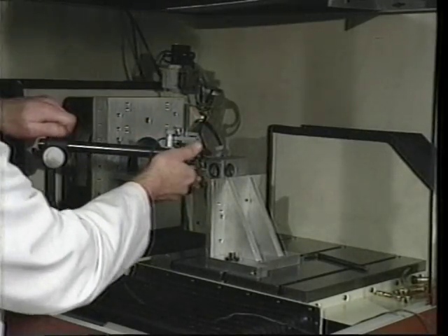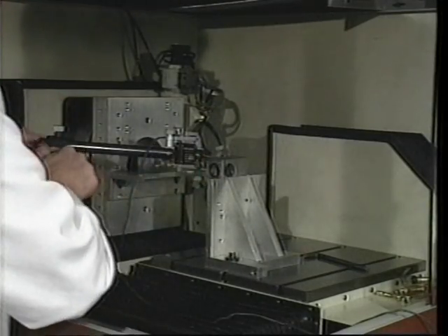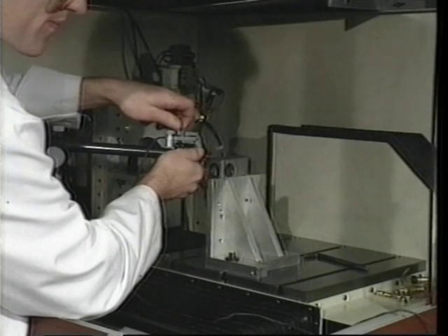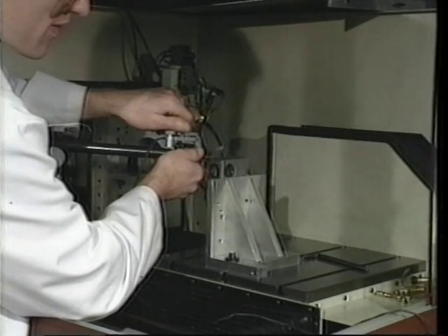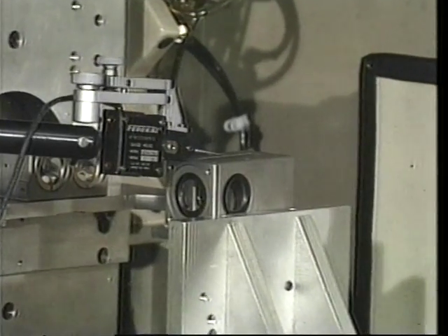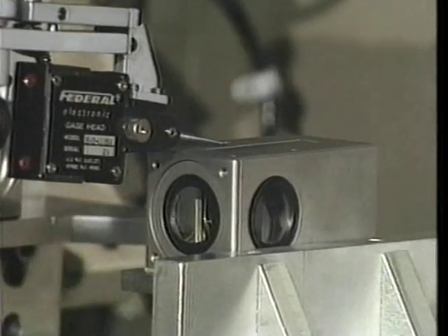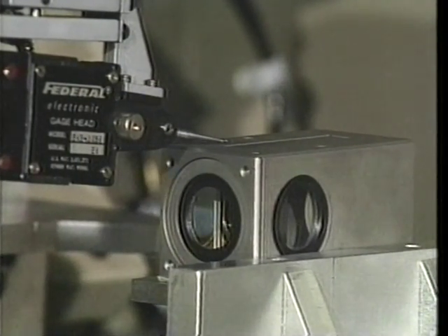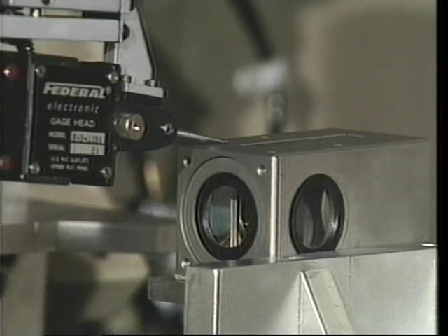The interferometer and reflector are aligned with the axes of motion in both the horizontal and vertical planes. Here, the interferometer is being aligned horizontally with the x-axis. The probe of an electronic indicator gauge is set up to traverse along the surface of the optic housing in the x direction. The optic housing provides a good reference since the optical elements have been assembled in the housing to within plus or minus 2 degrees.